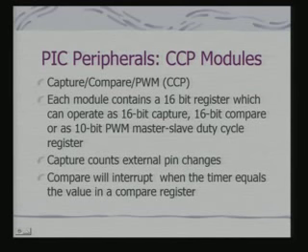Each of these modules contains a 16-bit register which can operate as a 16-bit capture register, a 16-bit compare register, or a 10-bit PWM master slave duty cycle register. Capture counts external pin changes, and compare will interrupt when the timer equals the value of a compare register.